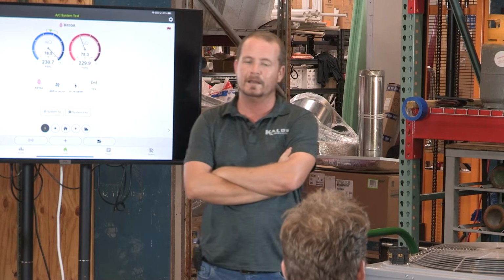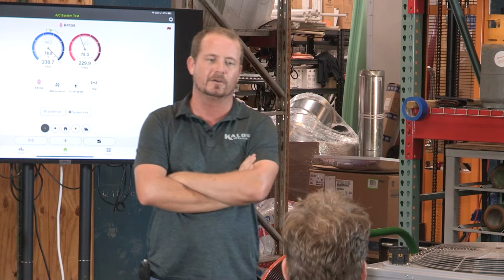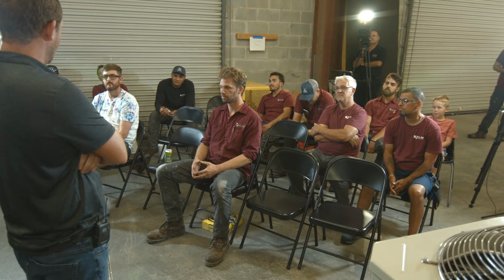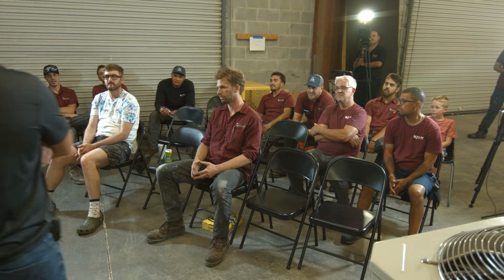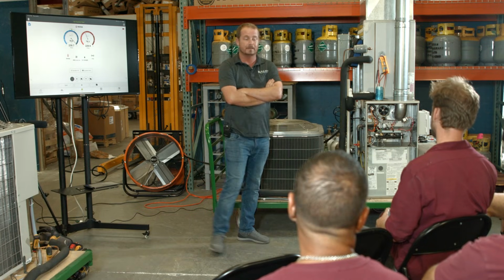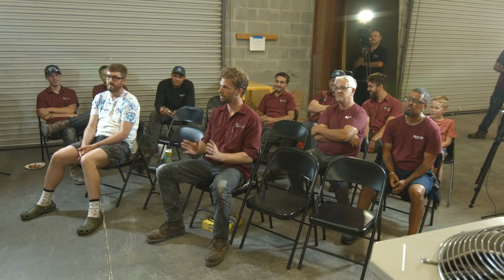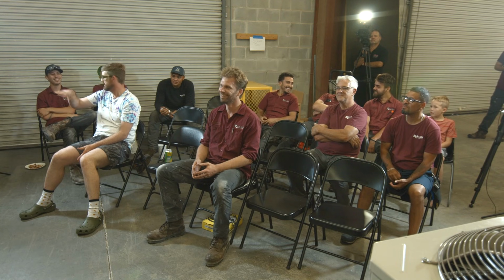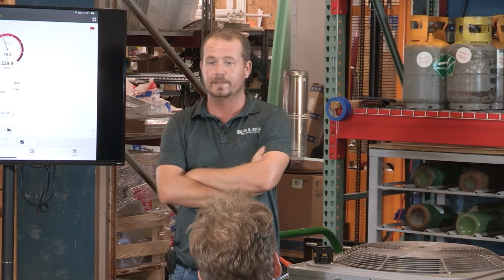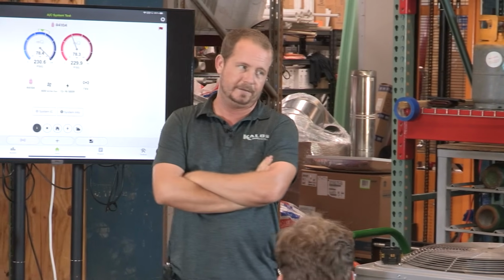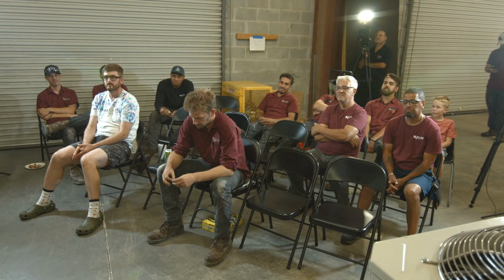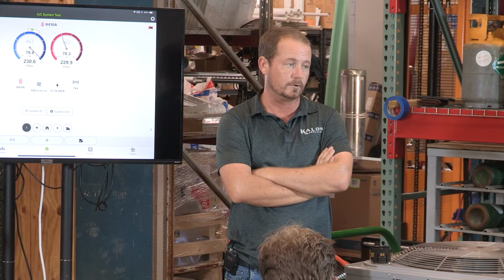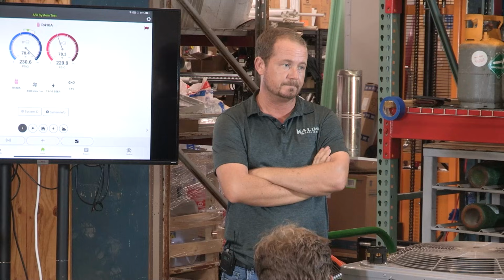What's another one? Why do you sometimes have really bad system airflow right after you had a backed up drain? Water in the return blocking it. Water in the supply. Water in the return, yep. Either way, if it's downflow, it could be water in the supply, but especially in cases where you have a flex return, those flex ducts will hold a lot of water. Especially with trailers, the drain backs up and the flex holds a bunch of water. Those trailers will fill up with water and that will block either the return or supply. In the case of downflow, it could block the supply. Either way, it doesn't matter. If there's low airflow over that evaporator coil, it's going to result in problems, right?